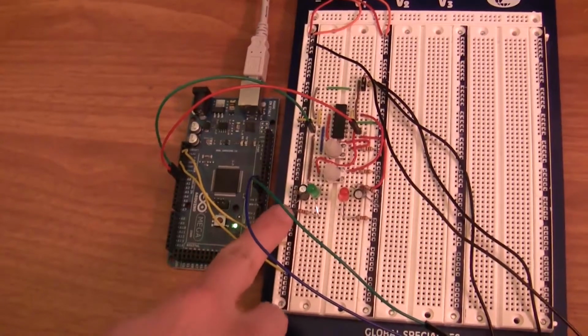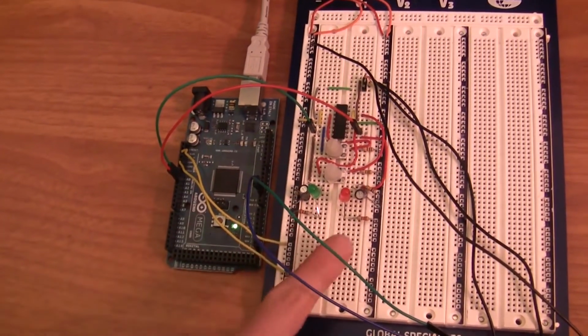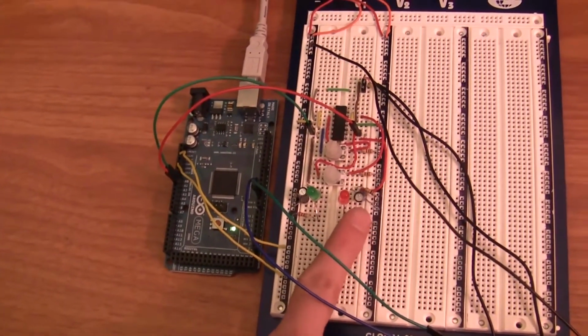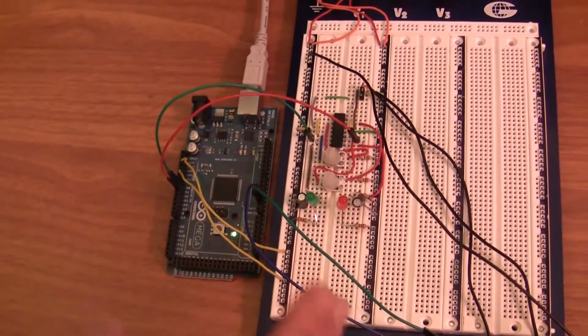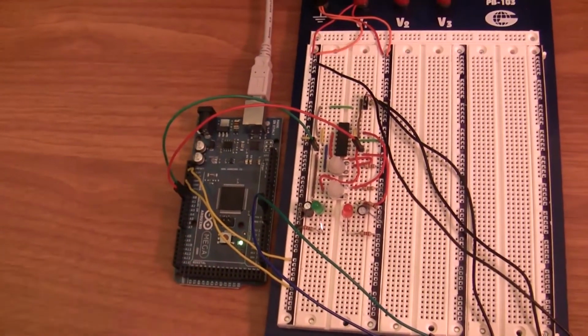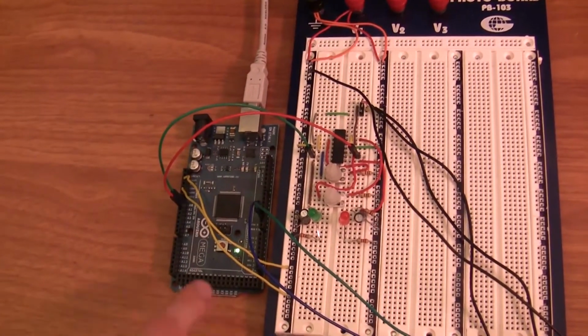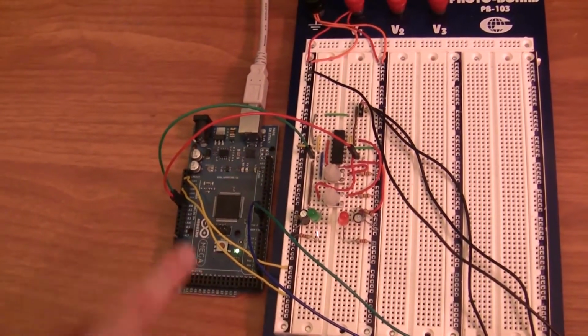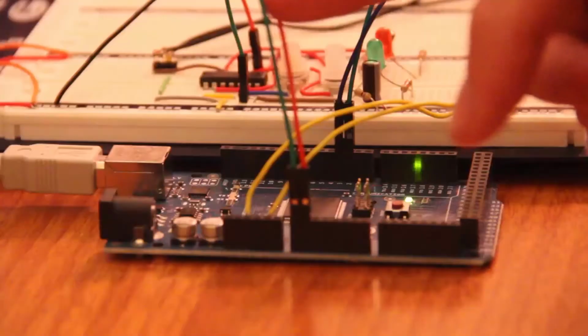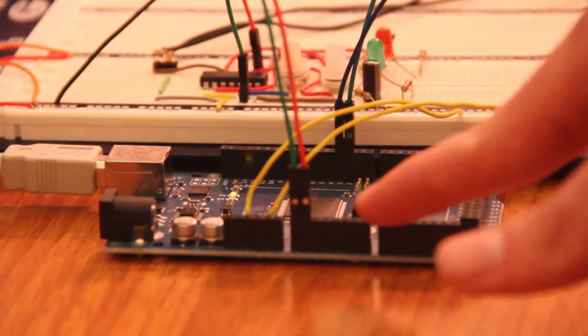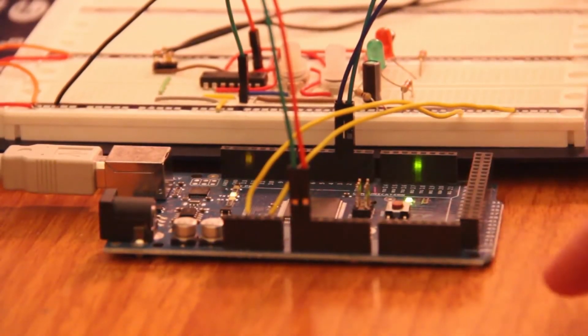Along with those, we have the resistors and our capacitors for our RC circuit, which remember is doing a low-pass filter that allows us to get the overall amplitude of the system without worrying about the particular frequency of the notes. So that's really useful for feeding it into the analog to digital converter of our Arduino, which is then happening with these 2 wires right here. They feed into analog pins 0 and 1 on the Arduino.